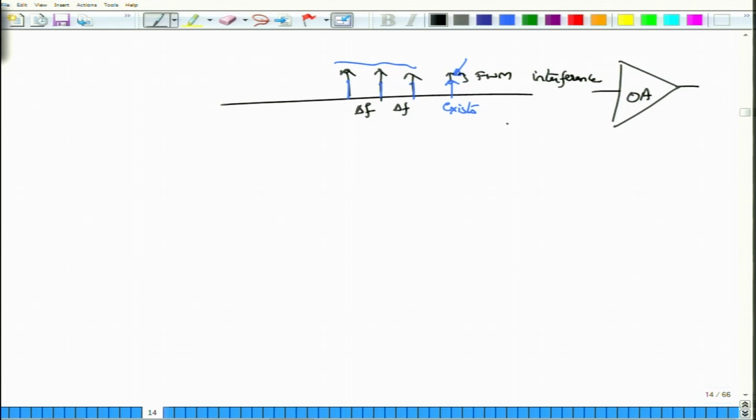That is the reason why gain equalization is so important, and this gain equalization will not happen when there is FWM plus those scattering effects that I talked about, SRS mainly, not SBS. So, when they change the gain, then they will lead to a lot of problems, because one channel starts to eat up the entire gain that is available for the other channel. So, there will be at the output all these channels which are not properly amplified, and therefore, this gain inequality will also persist at the output of the amplifier. So, this completes our discussion on nonlinear effects.